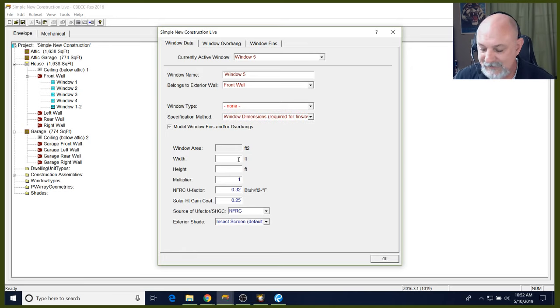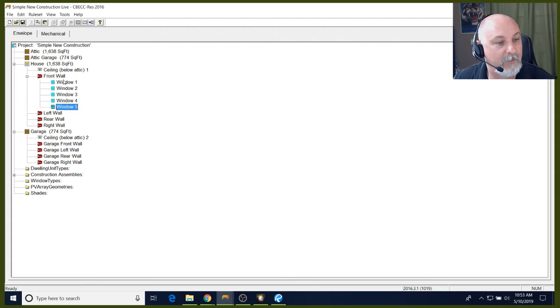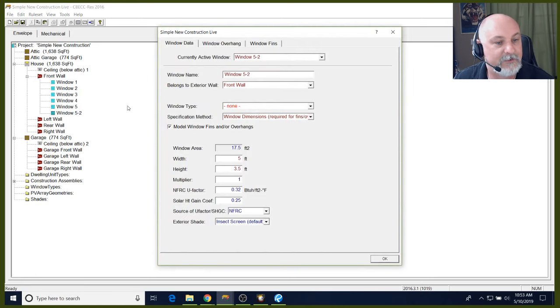I'm going to say that that's a 5 by 3.5, and it does the math for you. And if I had multiple windows, I could give it a multiplier. So I'm going to do that again, but I'm just going to use the Control-C, Control-V method. And that's going to be window 6.